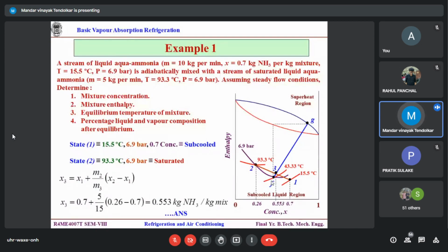So you have to satisfy two simultaneous conditions. Let's call this point, what do we call this? The equilibrium construction line, C. So F3G on a straight line and F3G as a right angle triangle, both have to be satisfied for the same pressure of 690 kPa.